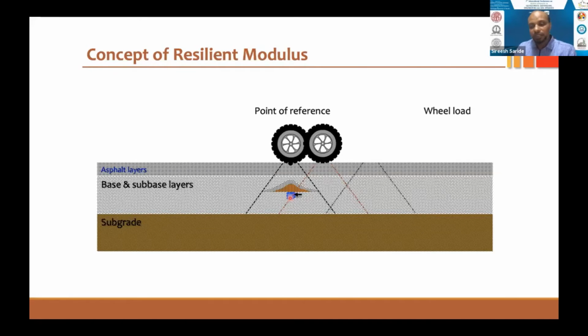So based on these combinations, and this is not only one tire here, the wheel that we are talking about, there are different classes of vehicles that we have, including from cycle to 18-wheel truck trailer, right? So the weights and loads coming onto this point of observation here would be entirely different when there is a different combination of vehicles that are passing on this pavement. So each combination will have a certain weight and stress conditions on this element.